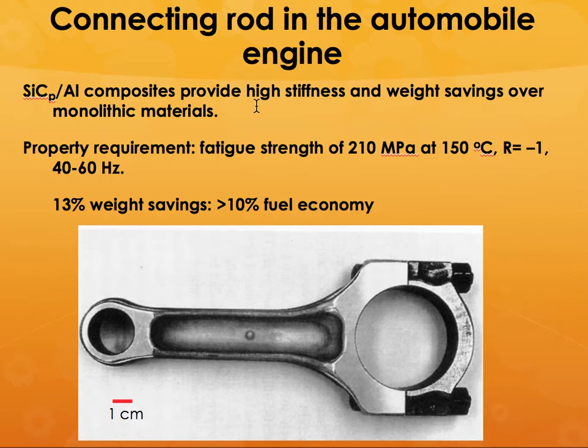So the only requirement is that it needs to have a fatigue strength of 210 megapascals at 150 degrees centigrade. And it has been estimated that 13% weight savings gives you more than 10% fuel economy. Now, with all this, why aren't more car manufacturers, automobile manufacturers, using these kinds of applications? Mainly the cost, and the cost of proving this application, rather than anything else.